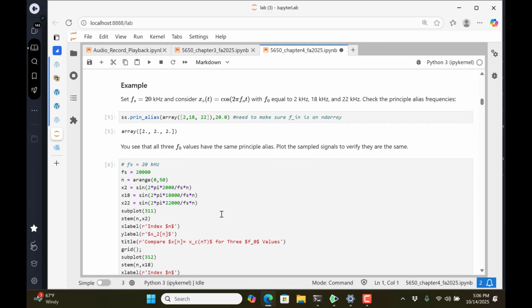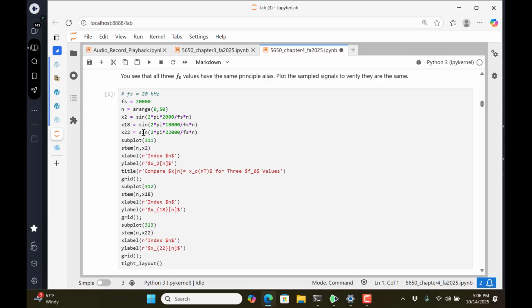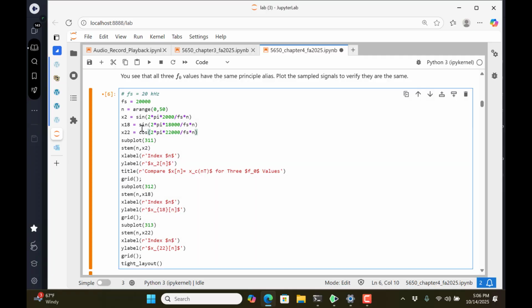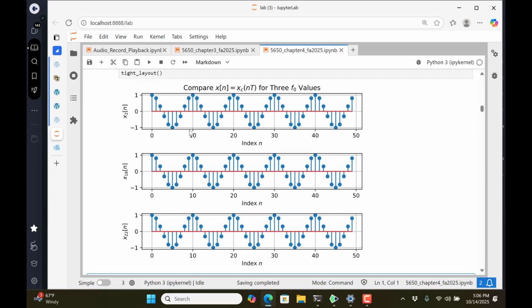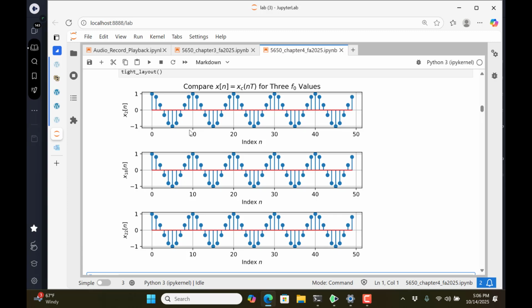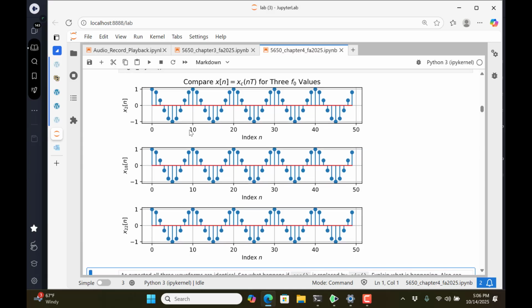And if you wanted to prove that to yourself, if I replace these with cosines, and ran it again, now it looks all the same because that's an even function, so it doesn't get inverted because of a negative frequency in this case. Sound good? I mean, it's negative modulo 2 pi is what it comes down to. You find the closest multiple of 2 pi to that frequency, and if it's sitting 2 kilohertz below, like it is in this case, that looks like a negative frequency.